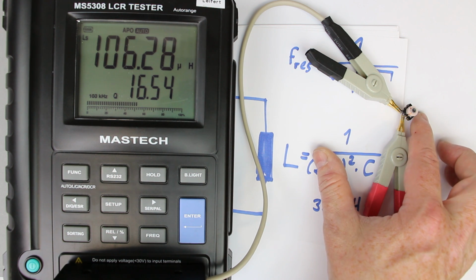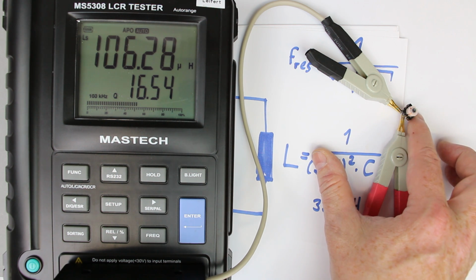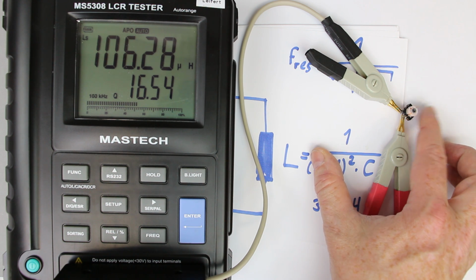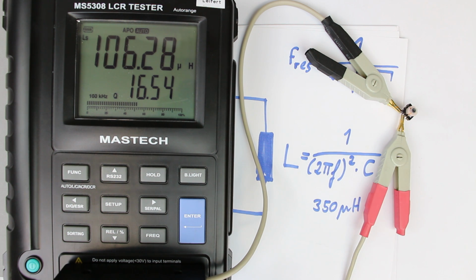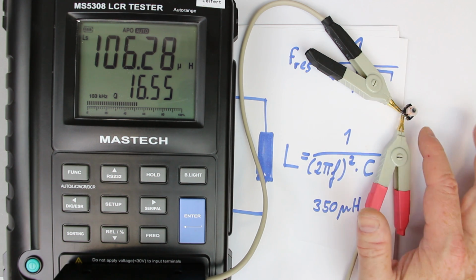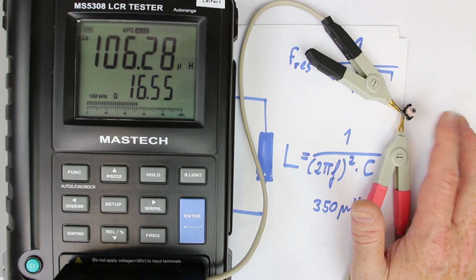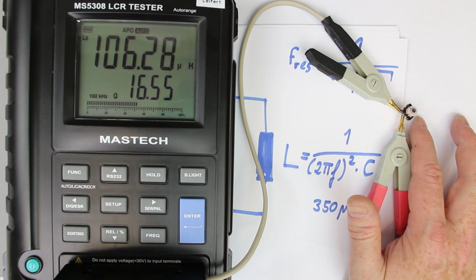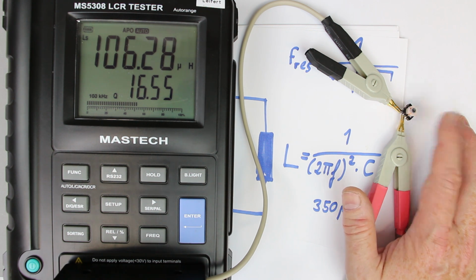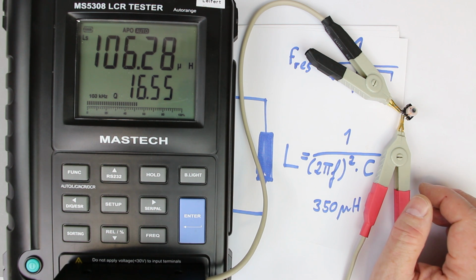This little coil originally was not intended as an AM reception coil. It had some other purposes, but with the right capacitance setting, it can at least be used for a great part of the AM spectrum. So it's quite a compromise, or a dual use coil, originally intended for a metal detector kit, but also usable as a miniature AM antenna, at least for part of the spectrum.